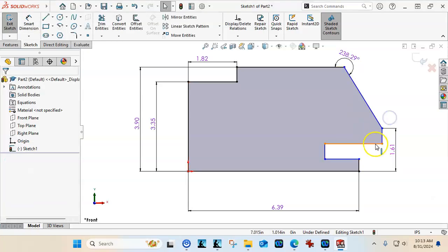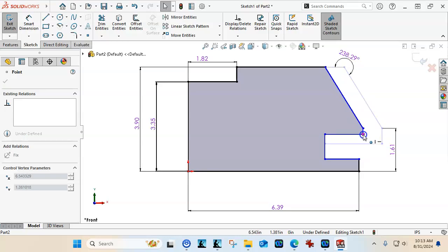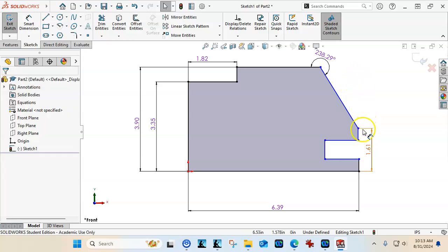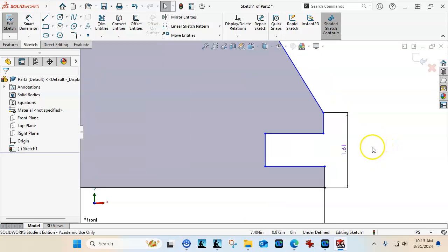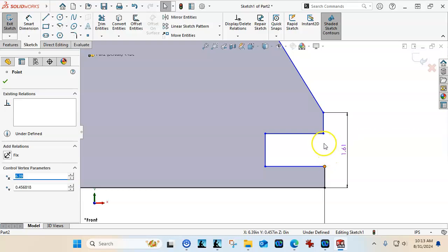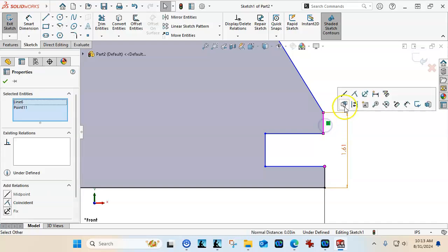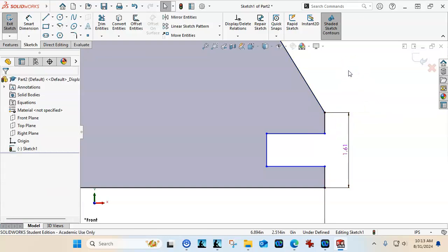Okay, so I'm not worried about this moving around. We're at that place where we can go ahead and pick which type of relation we want to add. So the decisions are: if I go point and point, that is vertical. If I go point and one of the lines, that would be coincident. And then if I go line and line, that's collinear. I still like the bigger target of the objects, so I would probably stay with that one.